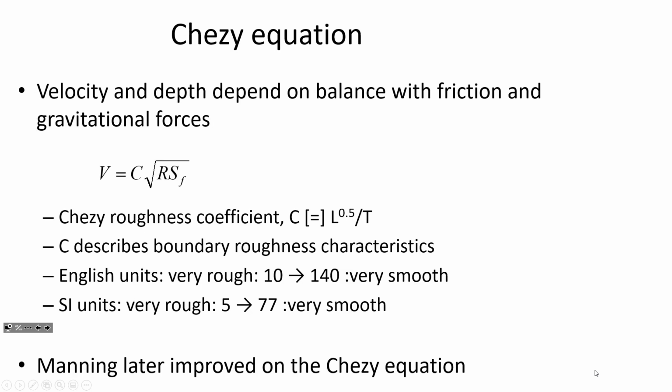Okay, so we're talking about resistance to flow. The fact that when water flows through a pipe, the pressure is decreasing in the direction downstream. For a horizontal pipe, somehow the interaction between the fluid and the pipe itself is extracting energy. There's energy loss as the water goes through that conduit. And there's lots of different ways that hydraulic engineers can account for the rate of energy loss.